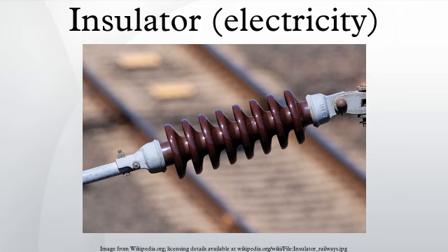Consist of a number of porcelain discs connected in series by metal links in the form of a string. The conductor is suspended at the bottom end of this string while the other end of the string is secured to the cross-arm of the tower. The number of disc units used depends on the voltage.